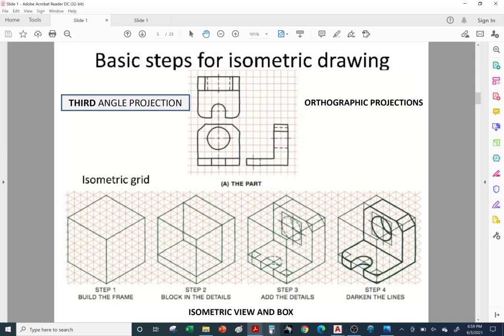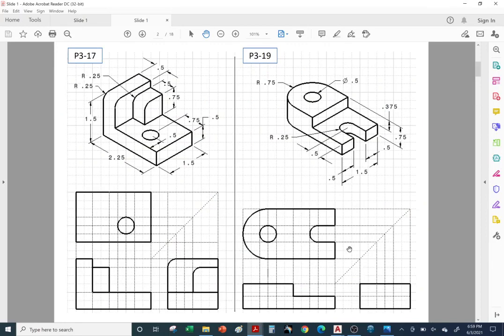All right, so let's go back. Okay, so we have an overall height of 0.75. We have a depth of 1.5. Actually, that should be in parentheses, 1.5, because we're double dimensioning with the radius of 0.75. Just double 0.75, we get 1.5, so this should be in parentheses. Okay, so that's the depth. And we need an overall length, and I just realized we're missing a dimension. We're supposed to have a dimension from this corner to the center of the hole, which happens to be concentric with the arc. We would have that dimension plus 0.75.